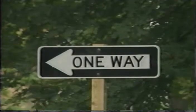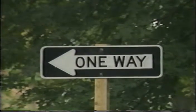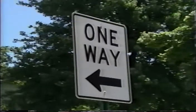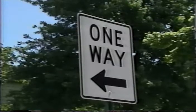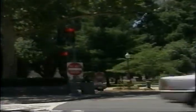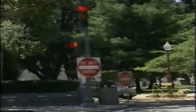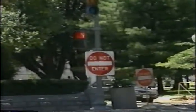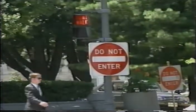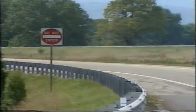One-way signs indicate a street where traffic may travel in one direction only. There are generally two kinds of these signs. Do not enter signs prohibit traffic from entering a restricted road section. It is usually a conspicuously placed 76 by 76 centimeter sign. Major streets and freeways may have a larger one.